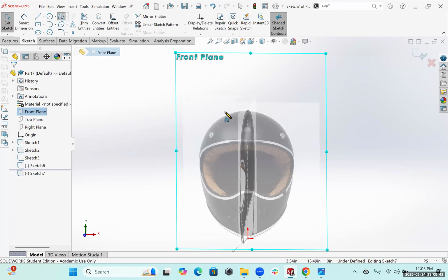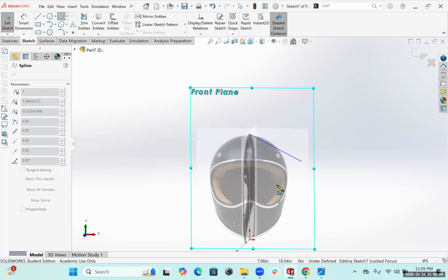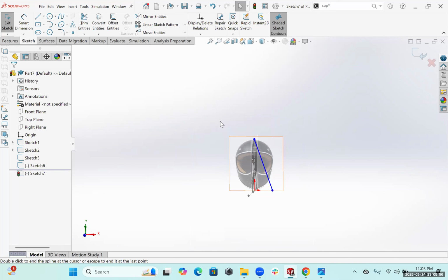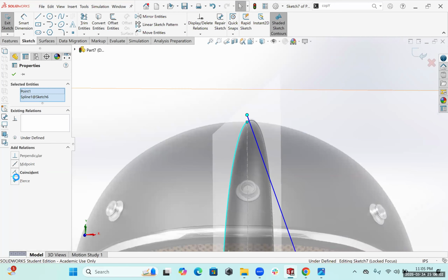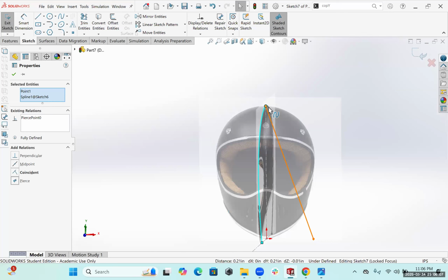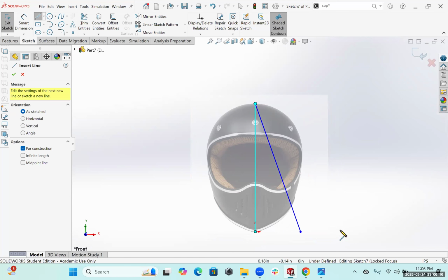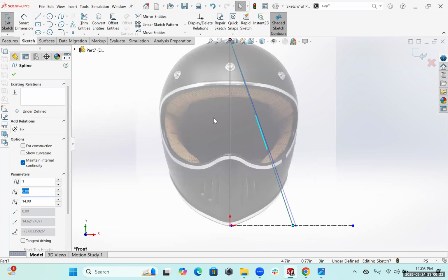One more time, spline. Here you need to make sure you're connecting to the end of these. If you want, you can always click above and then come pierce it later on. I'm gonna set this out here. Now you can set this at that point and make it pierce. So I know 100% that they're laying on top of each other. So we'll press Control 8 so I can look straight. Make sure that my bottom is at the right point. Here, yeah, and that's correct.